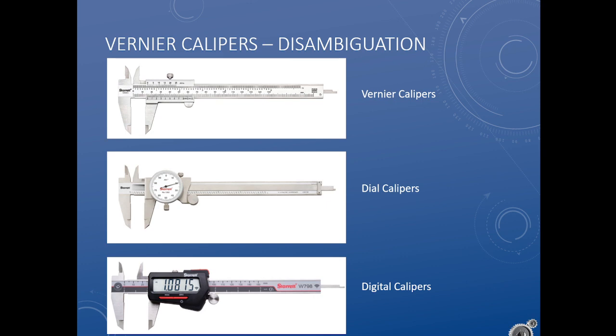Is there anything that vernier calipers offer that digital ones don't? Waterproofness. That's basically it. Digital calipers are in almost every way the same or superior to vernier calipers, at least good ones are. The thing that vernier calipers are is tough. Me personally, when I work in a shop, I have a pair of these in my back pocket, and I don't worry too much about it. My digital calipers, I keep in a plastic box with foam padding.